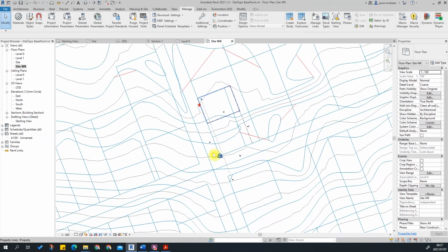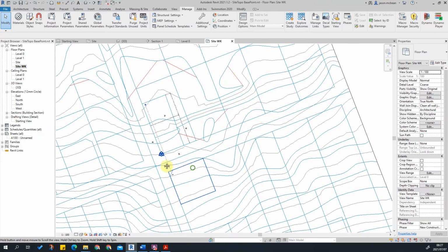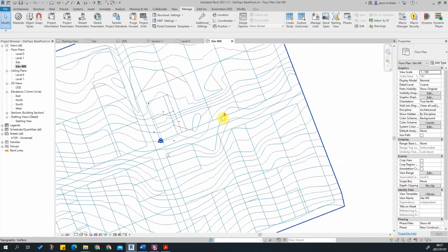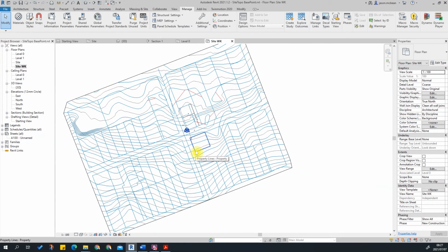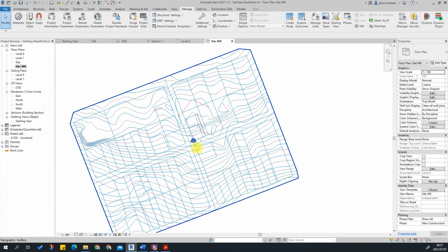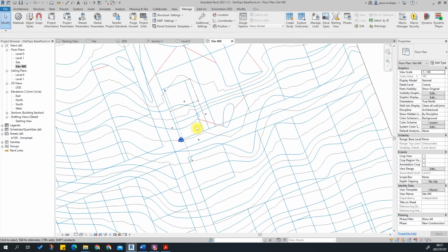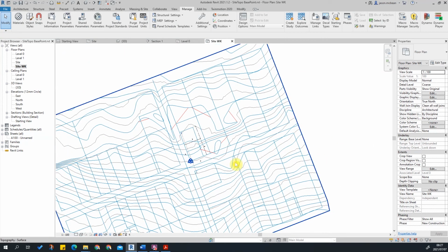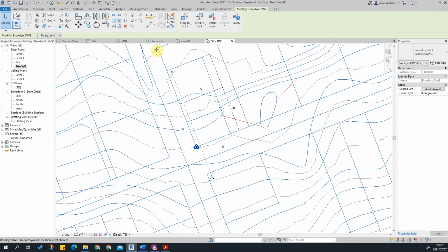Right, now that I've started to establish this information, I need to bring in some aerial photographs to start using that as well. In this case, I might switch to wireframe because the image will sit below everything. You don't want the image above everything else. The DWG file is fine over everything else, but the aerial photograph I want to bring in and also put underneath all this information. So the first thing I do with the AutoCAD file, once it's in, is pin it.